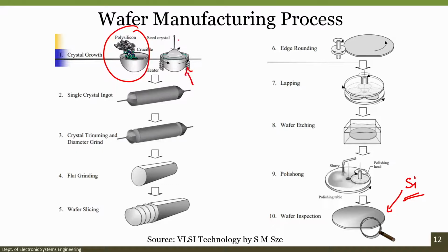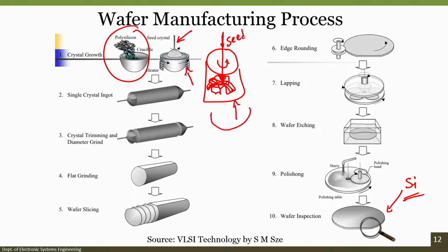Then you insert this seed crystal, it is a seed crystal like this, you insert it into this crucible, and crucible has the molten polysilicon, right. When you insert it down like this, okay, insert it down and you rotate it. So, this seed crystal, let us say, rotates in the anti-clockwise direction, then the crucible will rotate in a clockwise direction. So, it is opposite to each other.